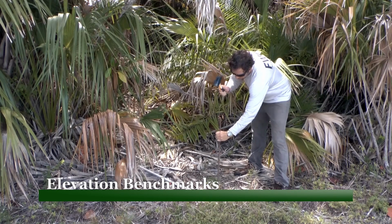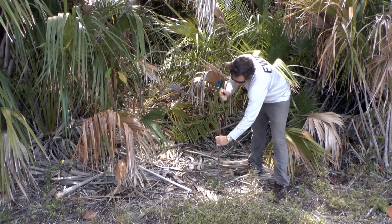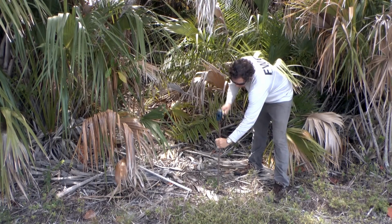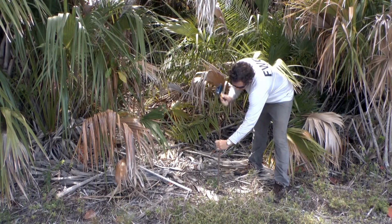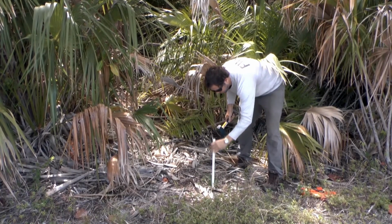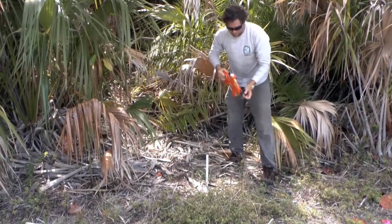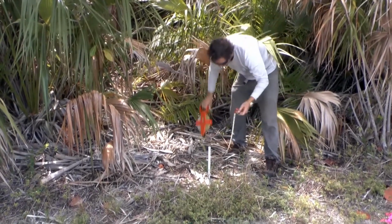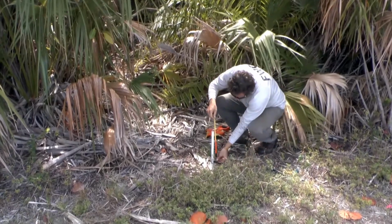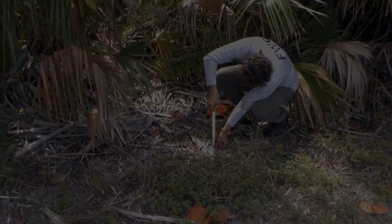Elevation benchmarks. Establish semi-permanent elevation benchmarks at the beginning and end of each transect. Benchmarks can be constructed from rebar, which is then capped or covered by a PVC pipe. Benchmarks should ideally be hammered to a depth of refusal, but that's not always practical in deep sediments. In addition to the transect, elevation should also be surveyed at the top and bottom of each benchmark.